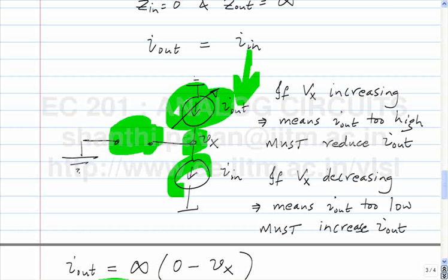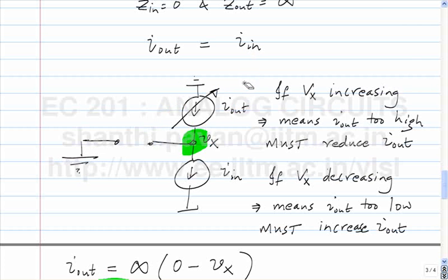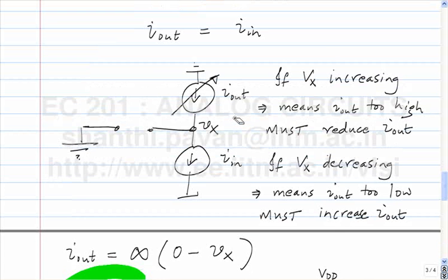So as far as the input current source is concerned, the potential across it is always equal to 0 regardless of how high the current is, which by definition is a short circuit, which is equivalent to saying that the input impedance of the current controlled current source becomes equal to 0 if Gm tends to infinity. Does that make sense?